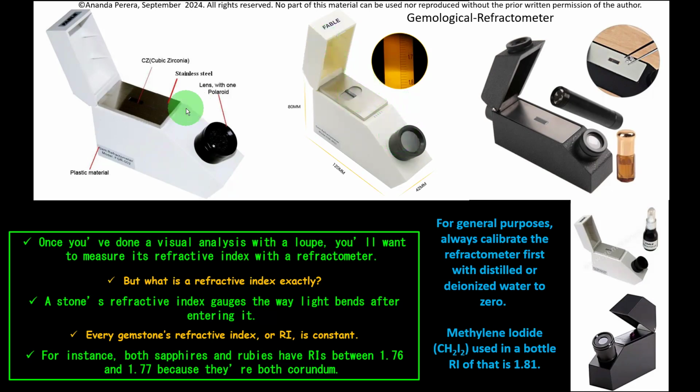After that, we have to cover this. This is the cover. Then we can see through this lens. The light goes through this. At the backside, we can set the torch here. Torch light we can use from here. Then we can see inside like this. There are two shadowy and light areas separated by the refractive index line. The scale is there. We can see this line to two decimal values or 3 decimal values. So this is called RI.